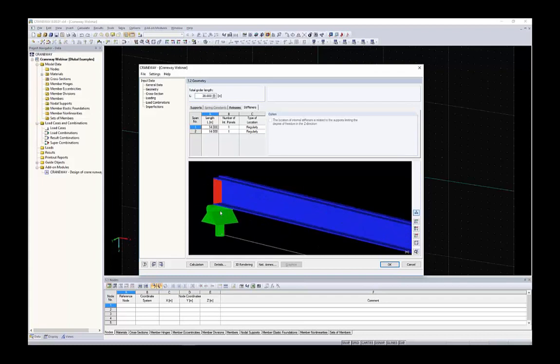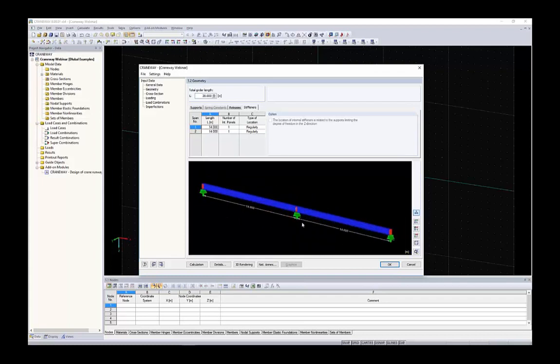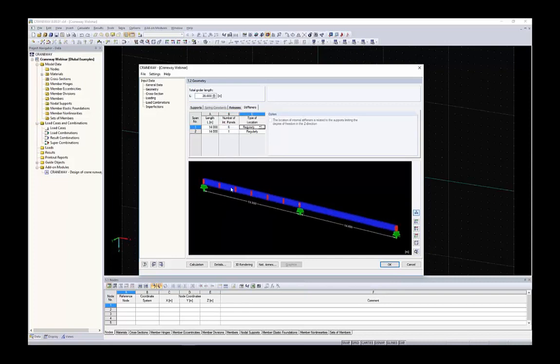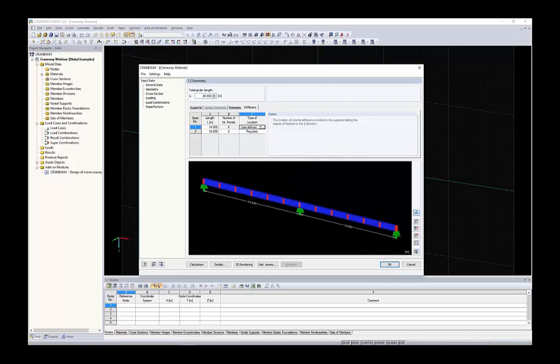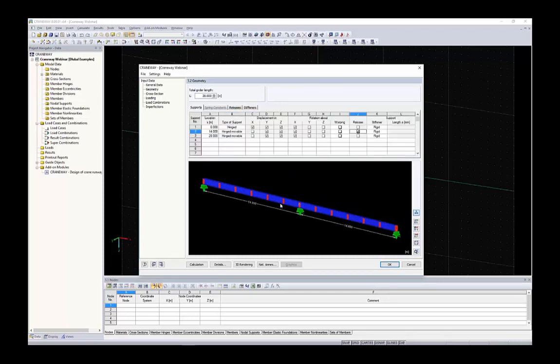The stiffeners over there are not for the calculation of the internal forces, but they will define the intermediate panels for the design of local buckling. So in this example, I want to have 6 intermediate panels on both sides as a regular, or you can even use user-defined and choose whatever distance you want. Okay, regular 6 panels, and that's okay with the definition of the CRANEWAY itself.